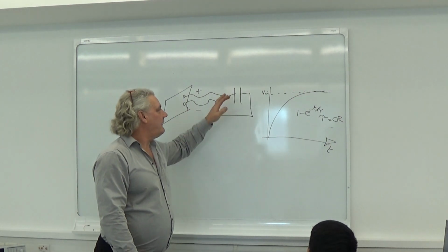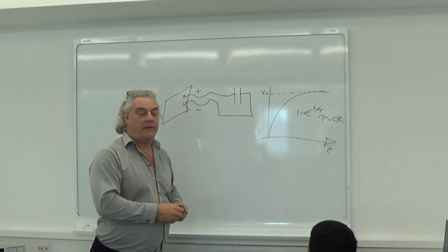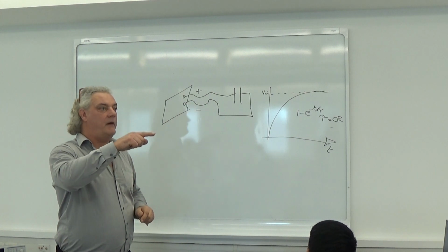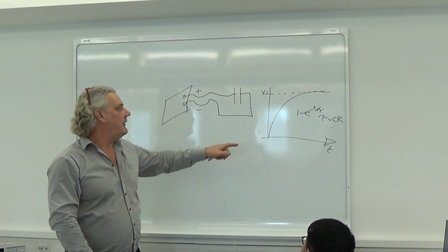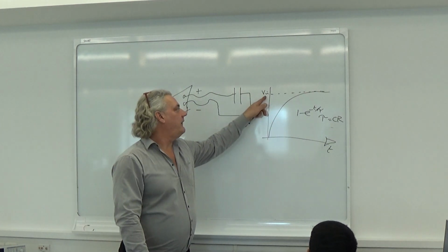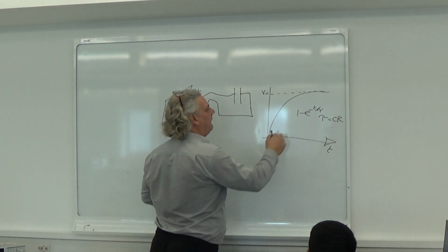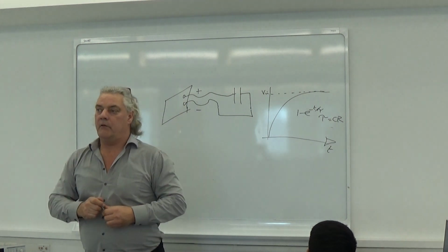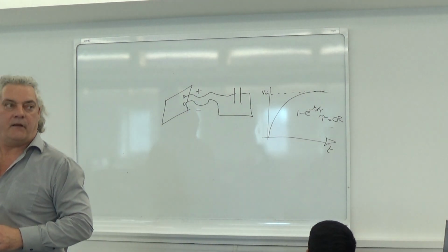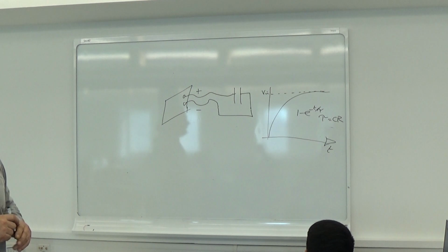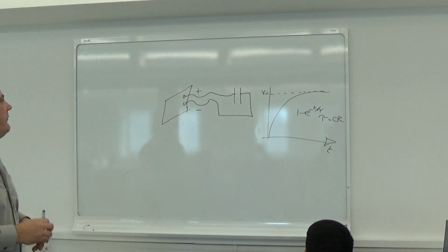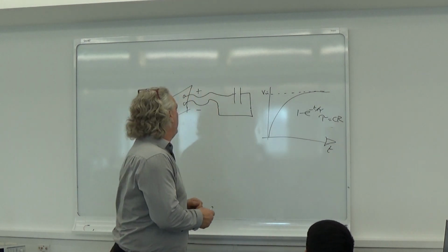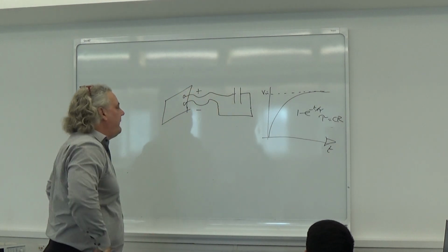But this circuit works, the capacitor charges up, it's what you expect. You put it into the window, you put your oscilloscope across it, and you watch a lovely curve going up the screen just like this. And it reaches what's called its asymptote, which is here, which will be the open circuit voltage of the panel for that particular level of light. Can't exceed it because there's not enough input, and it might take a long time to get there if you haven't got much light. Okay, that's fine, right?